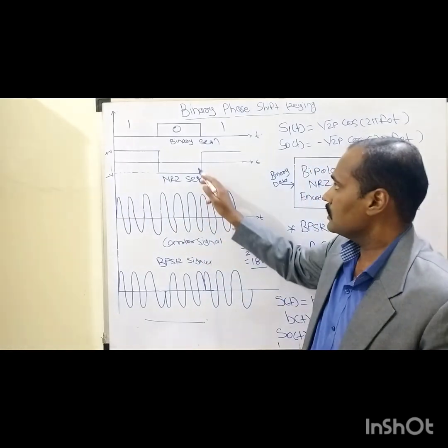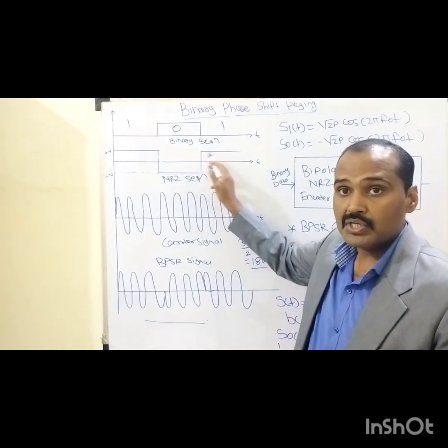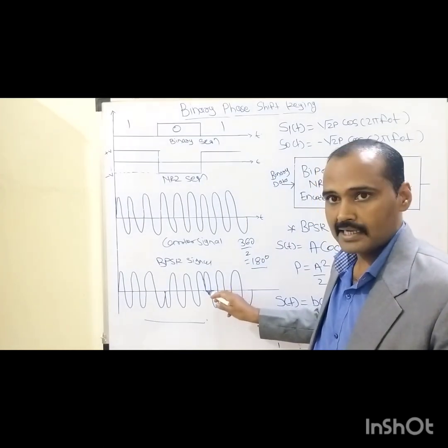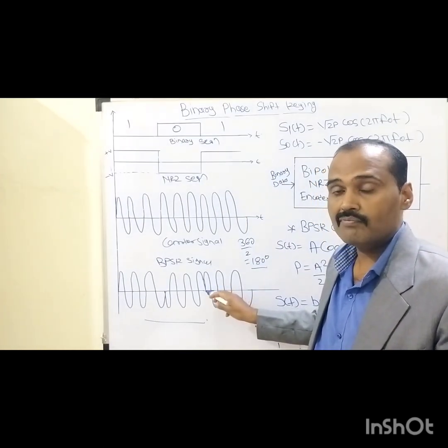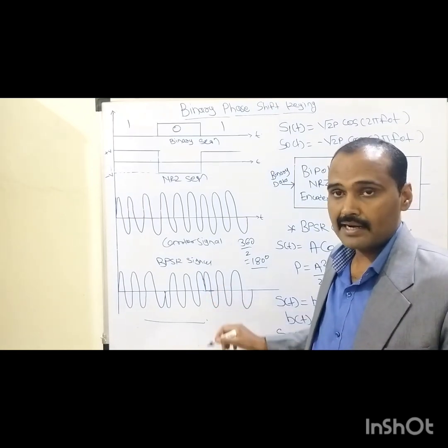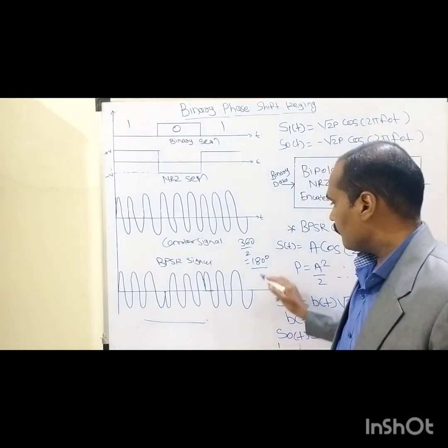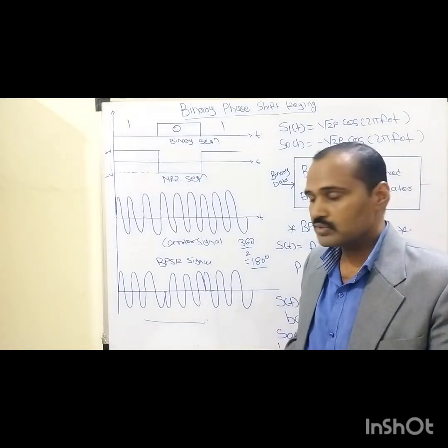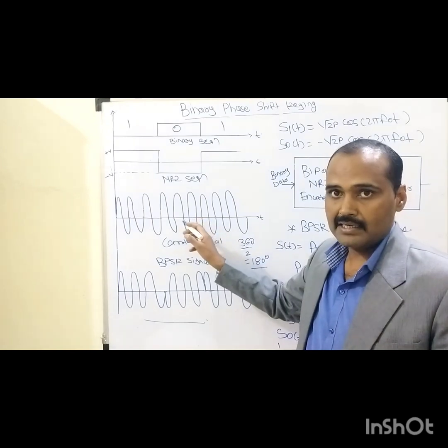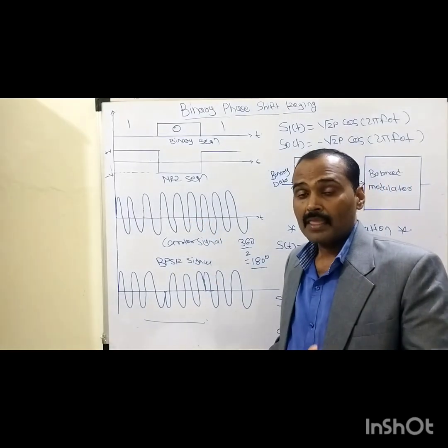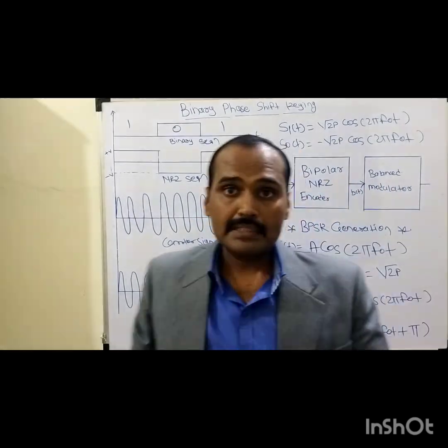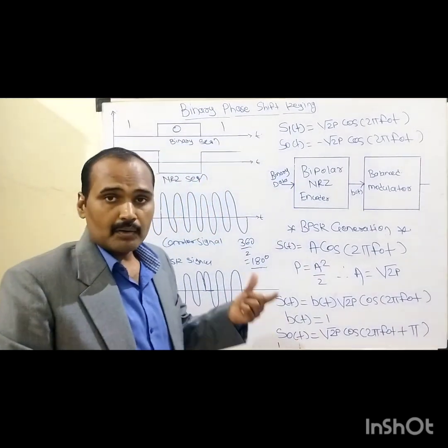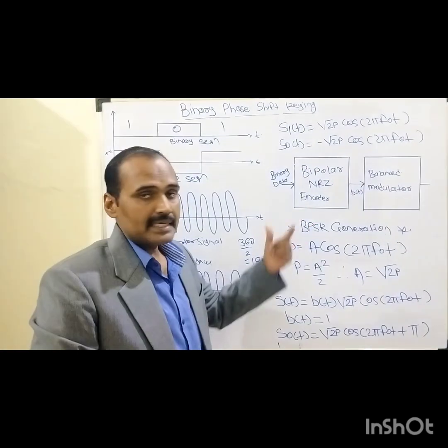Obviously, whenever we go through the signal transition from 0 to 1, at that time also the phase of the unmodulated carrier signal is changed by 180 degrees above the horizontal reference axis. So by an amount of 180 degrees each time we go through a signal transition, the phase of this unmodulated carrier signal is changed by this BPSK modulator, right? So this is the basic of binary phase shift keying, right? Now let us quickly go through the BPSK generator.